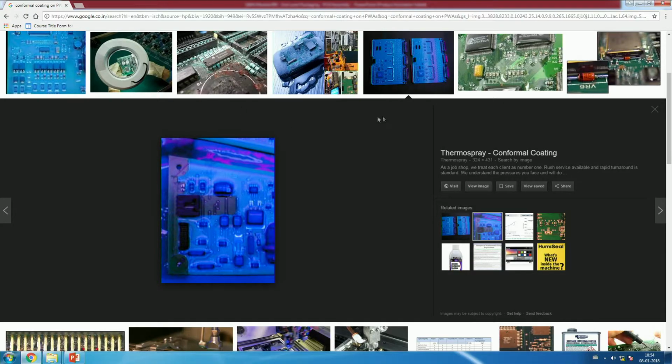Like for the IC, when you're putting a coating on top of an IC, the heat released from the IC to the environment will be blocked. Oh, excellent point, the thermal aspect of it. I didn't even mention the thermal aspect. So now you're trapping in heat, and absolutely right. Especially if you have heat sinks, it's very hard to put conformal coats on that. Excellent point. I completely missed that. Sorry, Anandaroop.